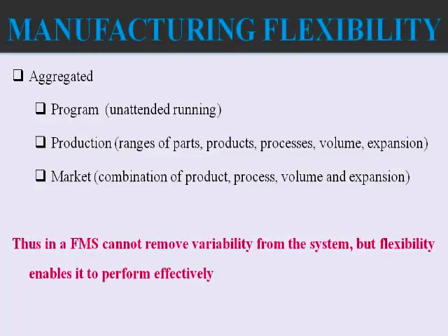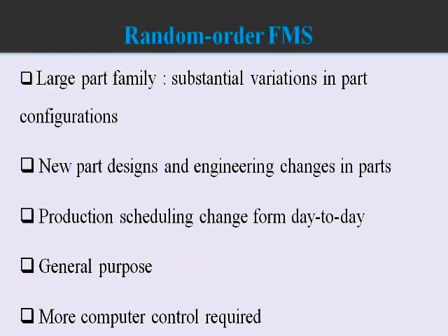Random order FMS: large part families and substantial variation in part configurations are allowed. New part designs and engineering changes in the parts are highly allowed. Production schedule changeover from day to day is allowed, and it generally uses general purpose machines, and more computer control is required.